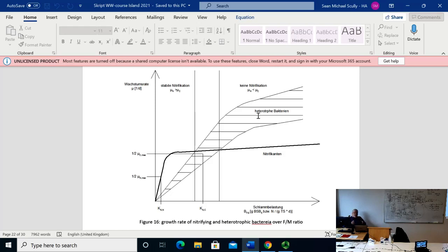And so finally you will fill up, the clarifier cannot thicken all the sludge, and the sludge will build up in the final clarifier until it just flows out of the final clarifier. So this is not what you want to get to. And if you now have a smaller growth rate of the nitrifiers, so let's say only 5 grow when you have 10 growing of the heterotrophs.